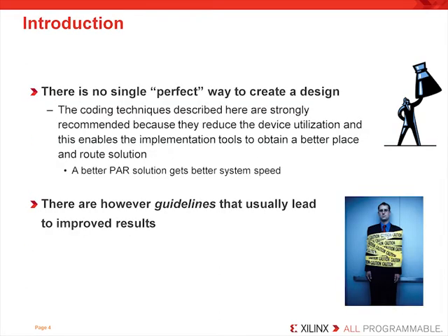We first want to point out that these are guidelines. They're not rules, so they're not perfect, but we do believe they will very often give you the best result. Now, these suggestions are especially important because Spartan-6 and Virtex-6 have a 6-input lookup table architecture and flip-flops that have some control signal limitations.